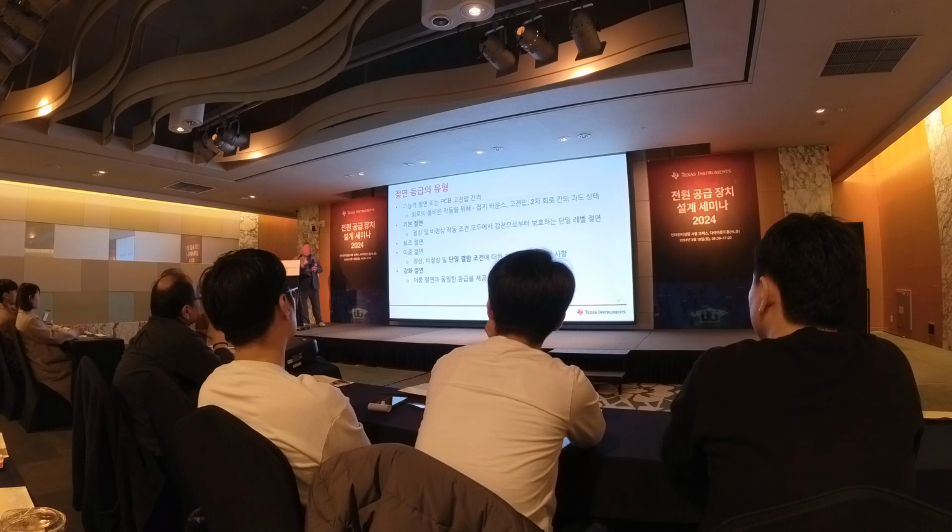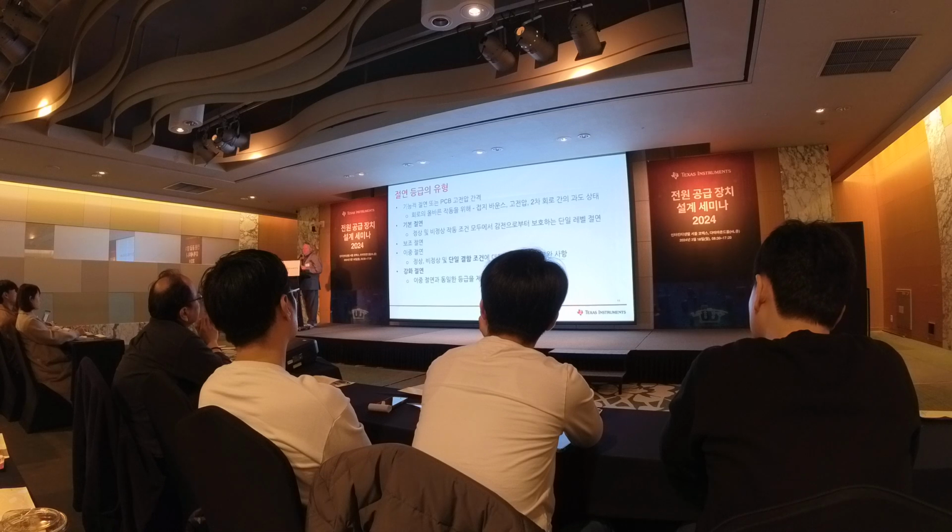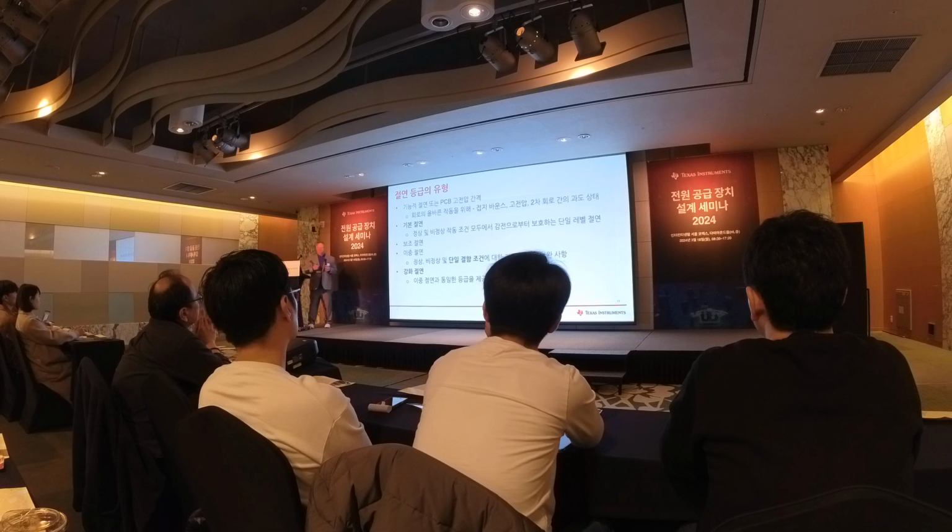And we have two types of these. It could be double insulation. Double insulation is the basic insulation plus a supplementary for single fault condition. And then the second type of supplementary insulation is reinforced insulation. It's a single type of insulation that provides double the protection, so double the ratings for insulation.